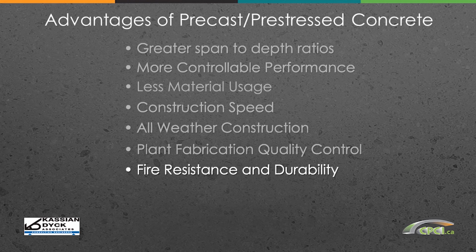Precast concrete is non-combustible and does not require additional fire protection, and this can result in reduced insurance premiums both during construction and in service. Precast is durable, providing a long service life, and its inherent resiliency due to its mass and high strength can provide protection from earthquake, tornadoes, hurricanes, and even blast loads.